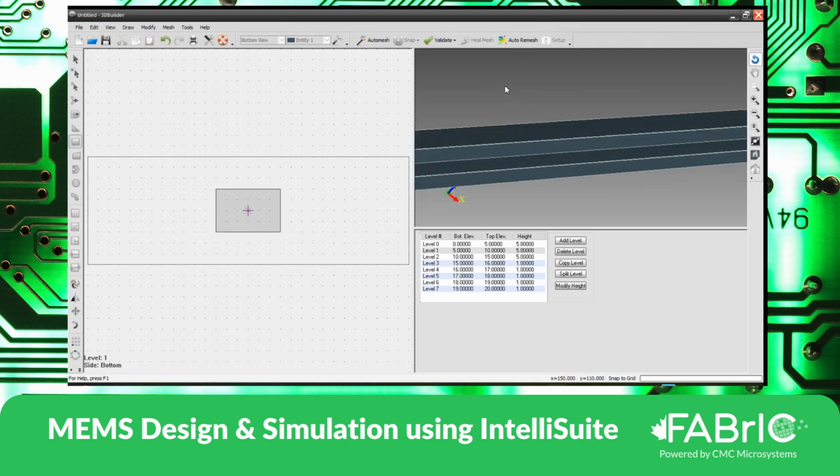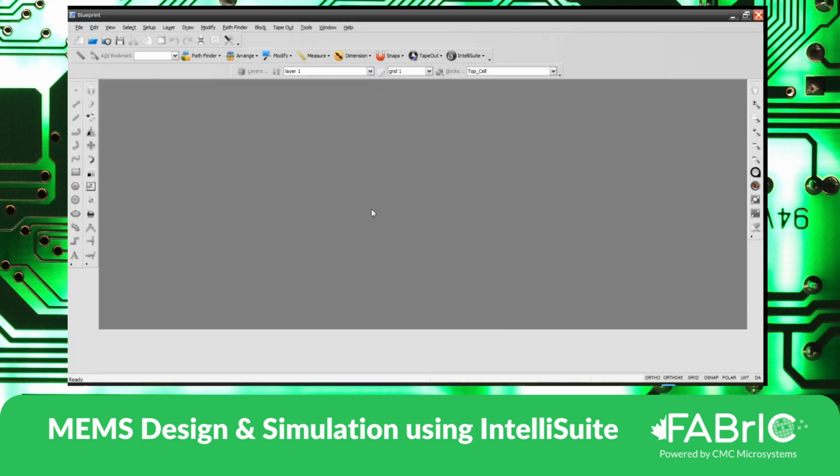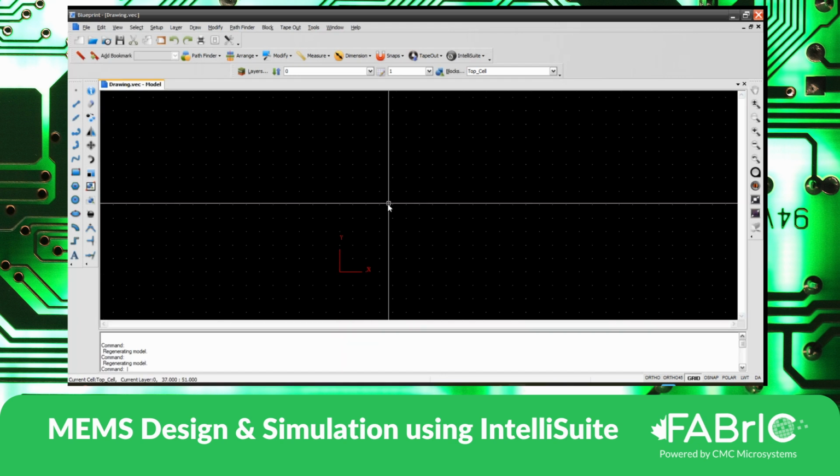So instead, what we recommend is in such scenarios, we always recommend to use the module called Blueprint. A blueprint is a layout editor which creates a 2D geometry, and the same 2D geometry can be imported on the 3D Builder module and define its thickness. So this will take care of my FEM issues.